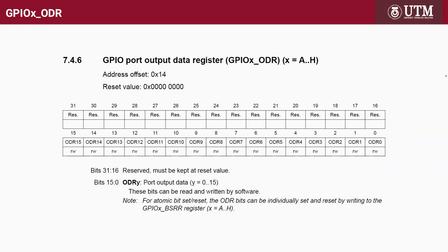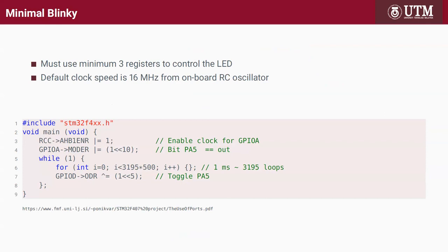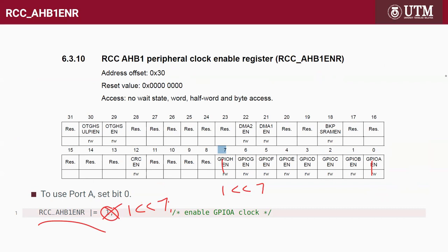So the unused space, don't touch it. Nothing happens if you send data there. All right, so to control the LED, first you have to turn on the port, enable the clock. We've seen this before just now, turn on bit 1.